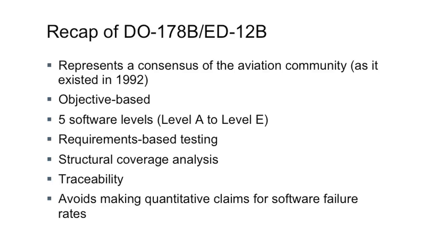So it really is very much an industry document, and it does represent a consensus of the aviation community as it existed in 1992. The second main point about DO-178B is that it's an objective-based standard. So it's not process-based and it's not evidence-based. It's objective-based. And by that I mean that it doesn't prescribe any particular software process. It defines objectives that your software process has to satisfy. And you have to plan a software process that's going to comply with the objectives.